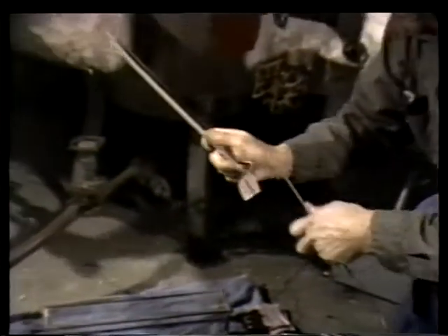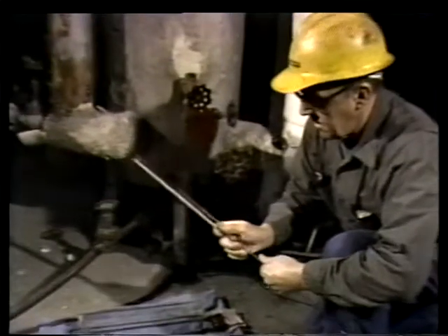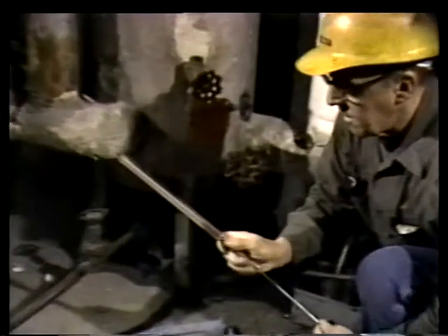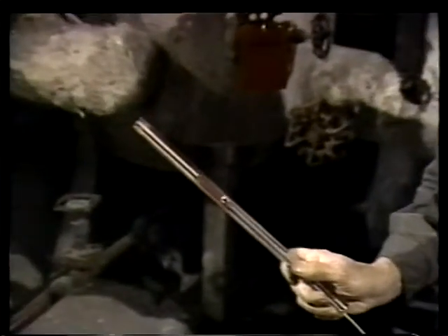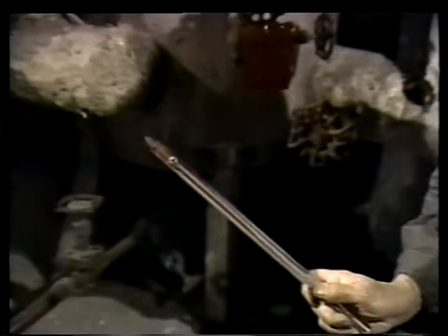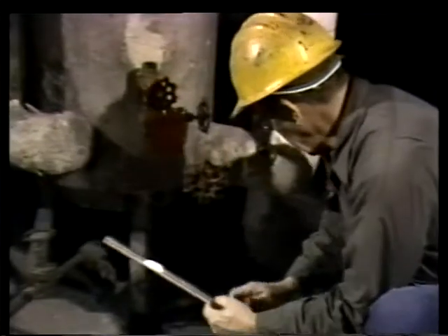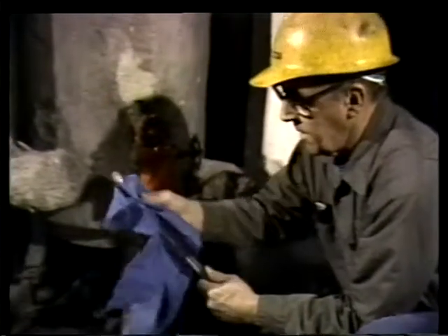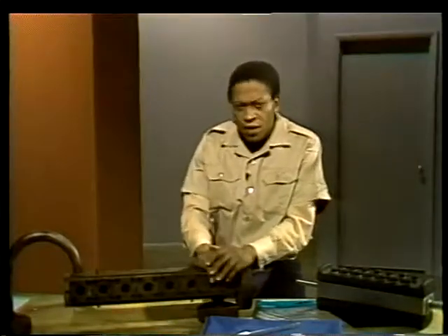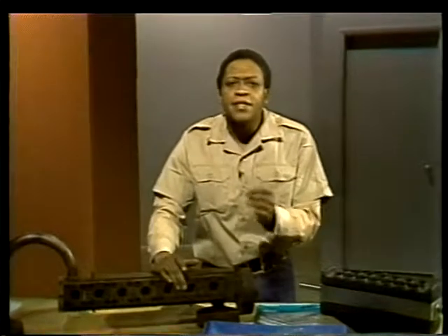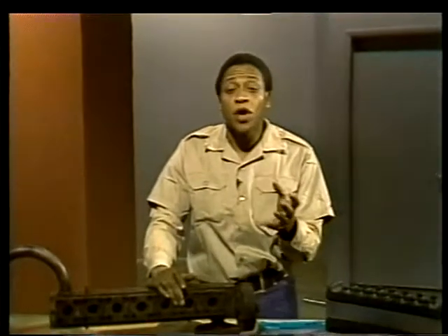At this point, the glass must be cleaned inside and outside. The inside can be swabbed out by pushing a clean, damp cloth through the tube using a rod as a ram. Be careful not to scratch or chip the glass while cleaning it. Now, if you find unusual deposits inside the glass, such as oil or metal chips, point them out to your supervisor. Deposits can be clues to other problems in the plant.